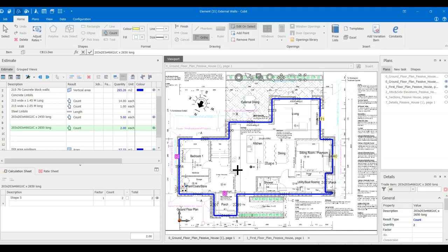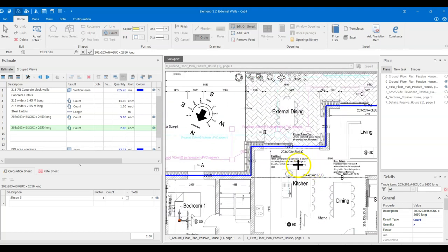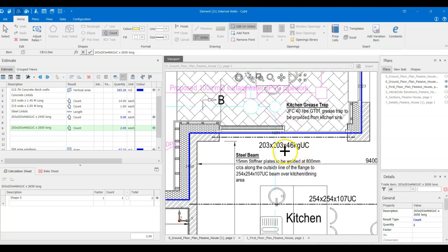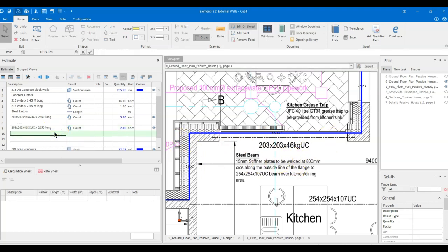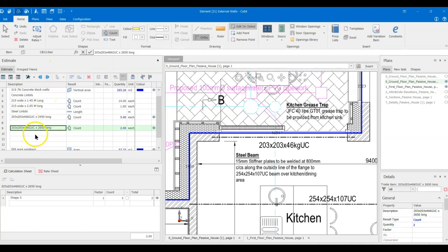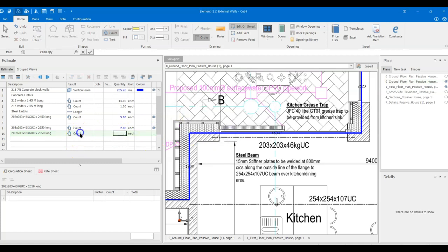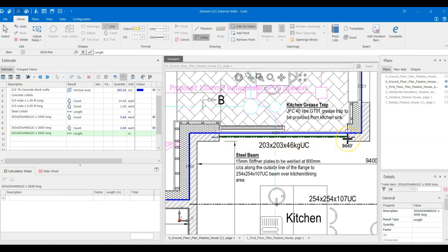Okay, now we mentioned earlier on that those ones there, we'll work our way up to the biggest ones. So there's one there. I have a stated dimension in there, 4634. That's for the overall. So I'm just going to check and see what that is. Is that 406? It is 46 kg. So I can copy and paste. And within there, I'll just take that out for a sec, deleting the quantity that was attached to that. I'm just going to double check the length of that first before I give it a description. So that's 3447. That's quite a big steel. 3.45. So I have to add on 450. So that's going to be 3.9. You can see that that's quite a big steel, almost 4 meters long. 3900.